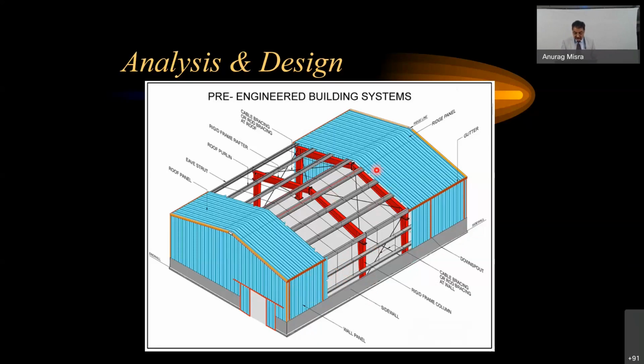You could also see some cross members because when the horizontal loads are coming, for these frames you have two options. Either you go for design of a moment resistant frame, or you create some mechanism which is taking care of the horizontal forces being applied on these structures. So to handle them, you provide the bracings which are able to carry all the horizontal forces and safely pass them on to the ground.